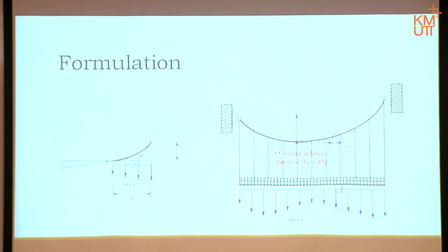So therefore, at this cut, we know the cable doesn't have shear force. A cable is a rope, right? The same mechanics, only tension. It cannot even take compression. Okay, axial force, that is tension only. So at this point, we will have one tension, and at that point another tension, correct? At the cut points, notice the direction will change according to the alignment of the point you cut.